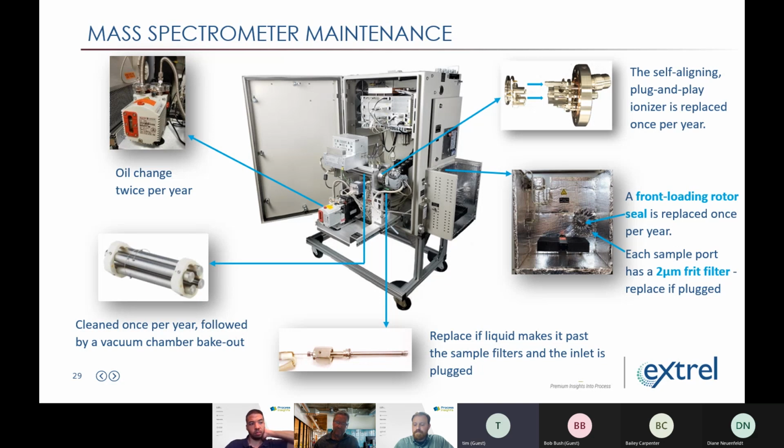And we've had pretty good luck. The flares are typically at one end of the plant or the other, and in our case, somewhat remote for safety reasons. We've had one problem with one orifice plate tending to plug up with, we think, scale. So we have to go down and pump it about every 3 to 4 weeks and make sure the taps are clear.